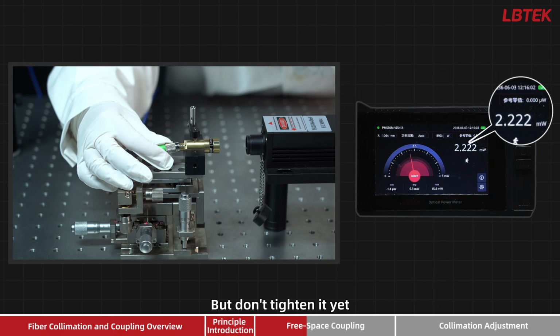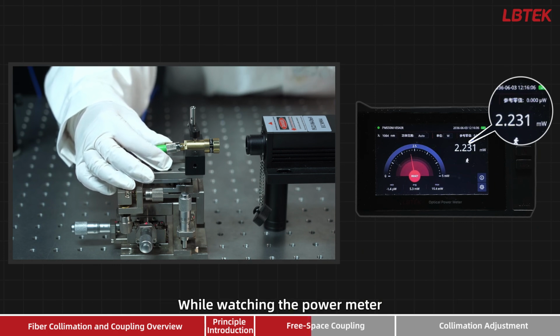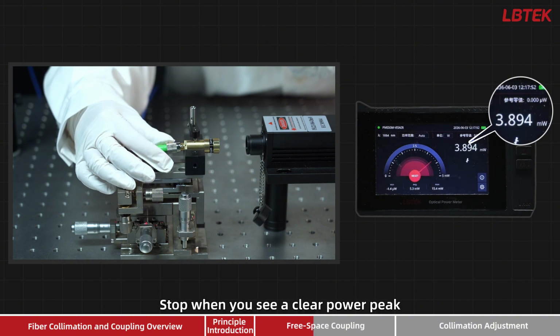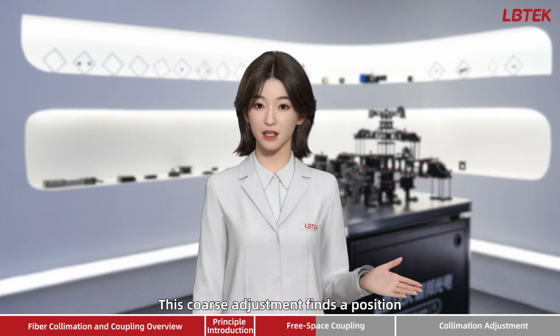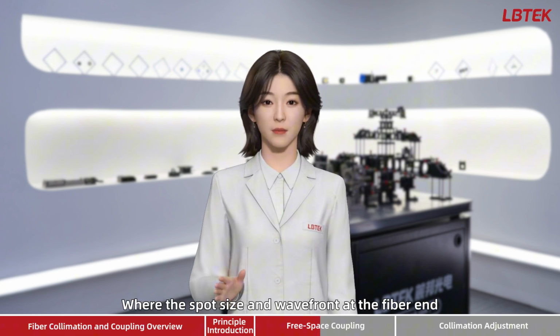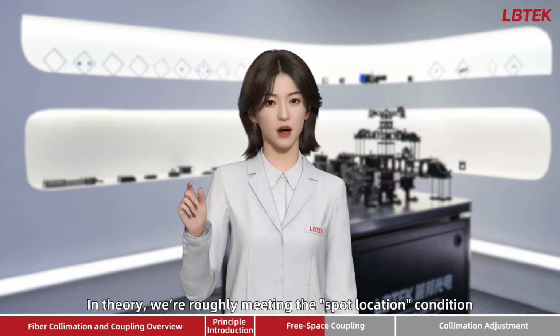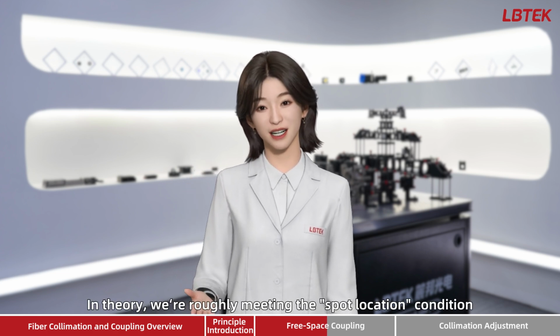But don't tighten it yet. Instead, move the fiber connector back and forth by hand while watching the power meter. Stop when you see a clear power peak. This coarse adjustment finds a position where the spot size and wavefront at the fiber end roughly match the fiber's fundamental mode. In theory, we're roughly meeting the spot location condition.